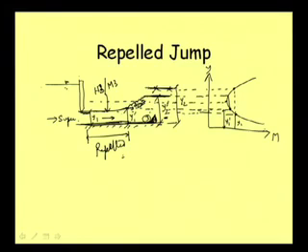Well, that topic is important. Of course, we may not get scope to deal with this particular topic, which is called the stilling basin. We construct some structure here, called a stilling basin, which ensures that the jump will form within a very close distance from the upstream structure. Well, we may discuss that briefly in this particular topic.